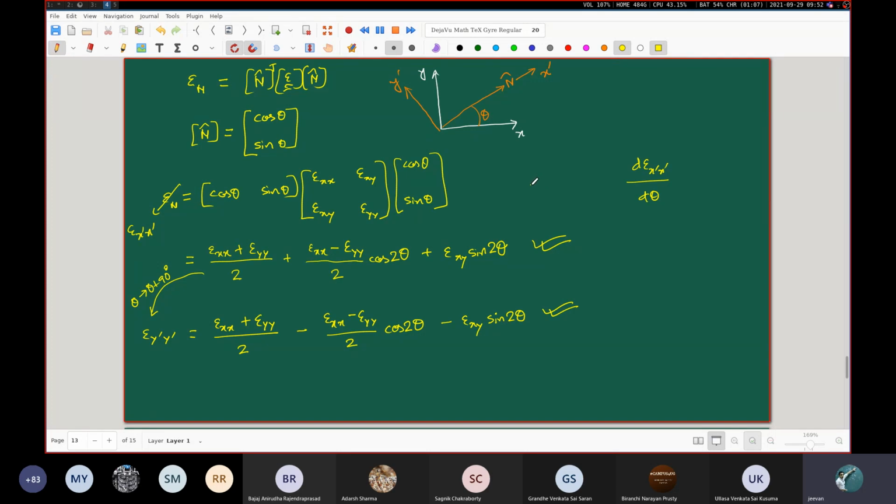Try to see that even though the formula may be the same for the stresses and the strains, the fundamental geometrical basis of them are completely different. The stress has to do with the cutting planes and the concept of traction. This one has to do with the change in the line segment magnitude and the line segment direction within a three-dimensional body, or equivalently a two-dimensional body.